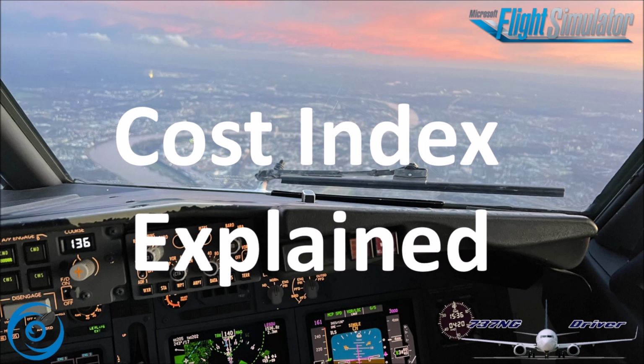What is going to be most noticeable, however, is that the resulting optimum and maximum altitudes are also going to have a significant change depending on the cost index entered. So let's have a look at the previous example again. If we would fly our 757 with a cost index of 0 under the given circumstances, then we would get a recommended altitude of an optimum 328, maximum 362, so flight level 362, and a recommended from the FMC of flight level 310.